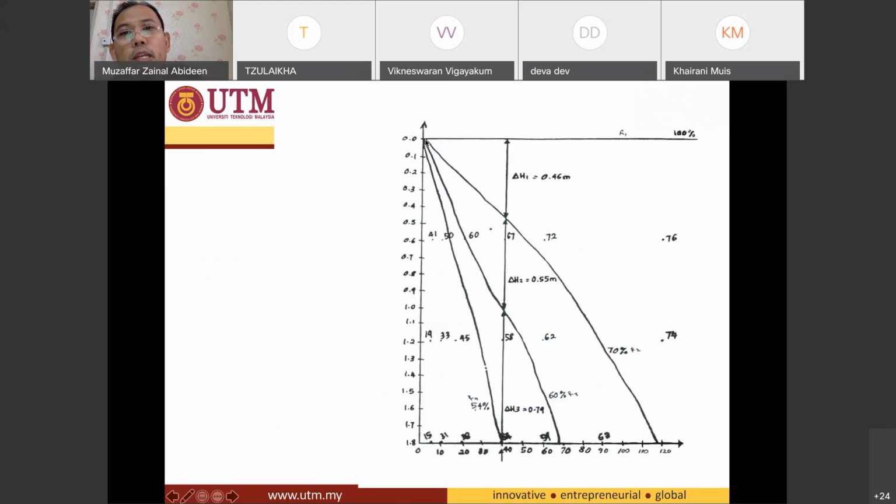These have been plotted. These are the iso concentration lines, if you can still remember. Along this iso concentration line, the removal is all the same. For this example, this line is 70%, the top line is 100%, and this one is 60%. The third line and the fourth line is 54% removal.